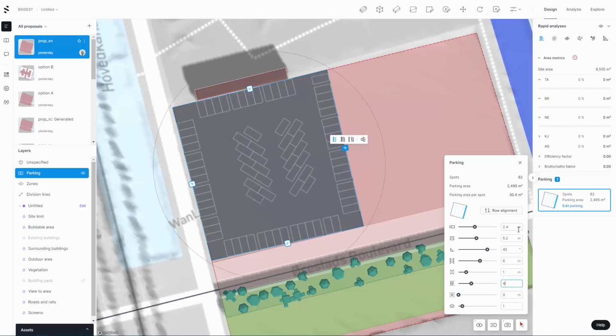If you're looking at 2.4, maybe you can get 3, because it might be a 9 meter span between column to column. But again, this comes down to the structural grid that you've adopted for your project, and this will come down to cores, it will come down to the unit layout. So car parking can be a fiddly one to get right when you've got that structure transferring down to the car park building. And then there's a buffer from wall.